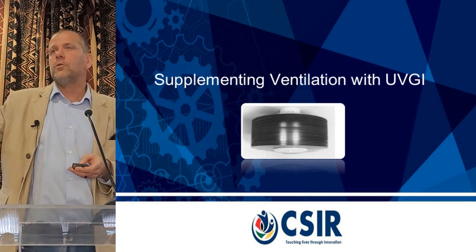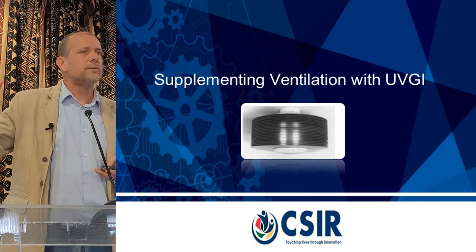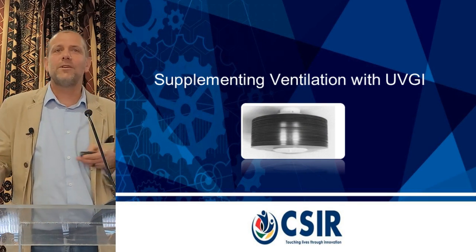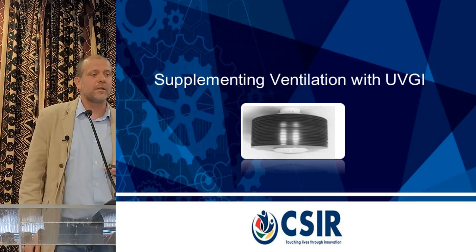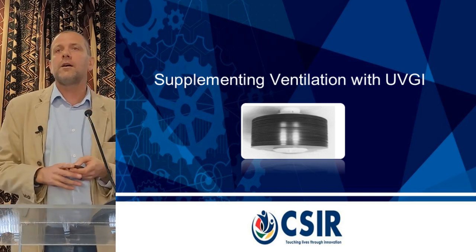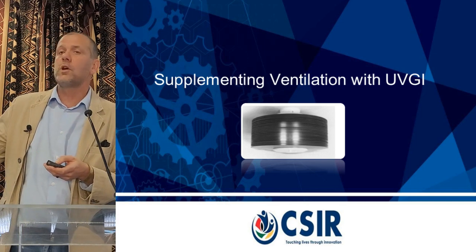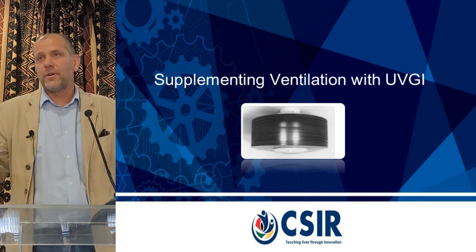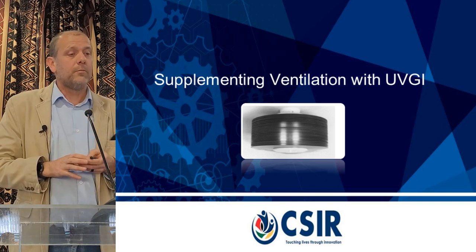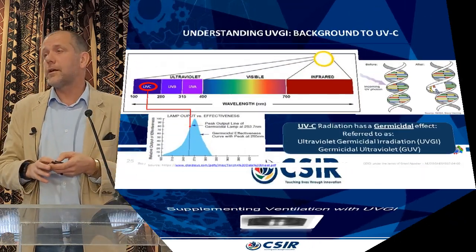But we've still got that shortfall. How much was the shortfall? Do we remember? About 800 liters per second. So we need to put something in there. For the days the ventilation system's not working well, or our natural ventilation system's not working, UVGI is a good candidate.